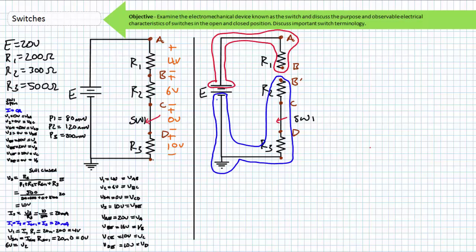All voltage will be dropped across these two nodes, B and B', basically the bottom of R1 and the top of R2. Ordinarily, these two terminals are hooked to the same node B, and it would be cause for concern to observe a 20-volt differential between them.